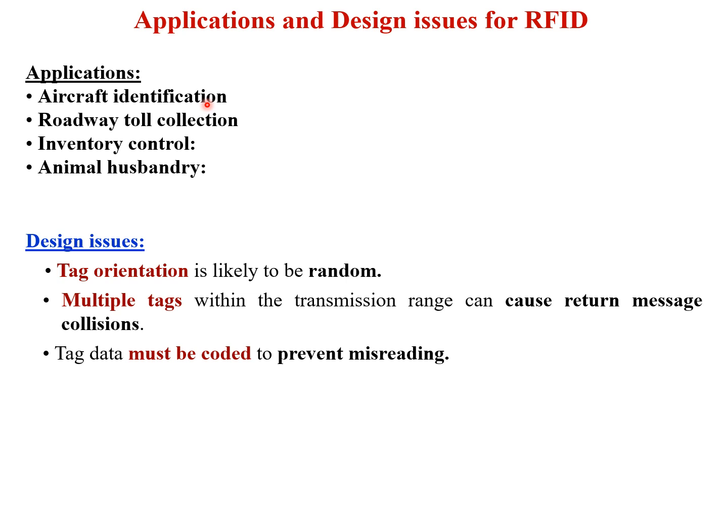A terrestrial terminal radar, for example, transmits a data beam in the direction of the aircraft. A transponder in the airborne vehicle responds by transmitting an identification code to the initiating terminal, which can be used to mark the radar screen. It is used in wartime to identify friend or foe.